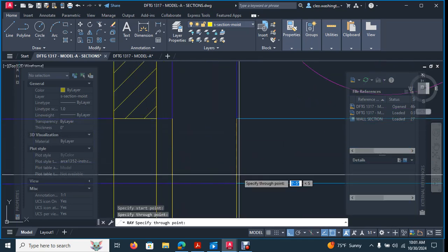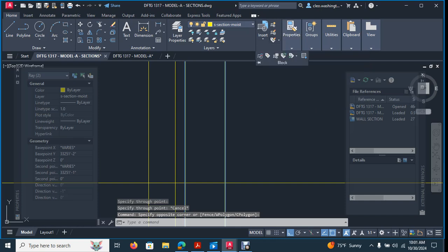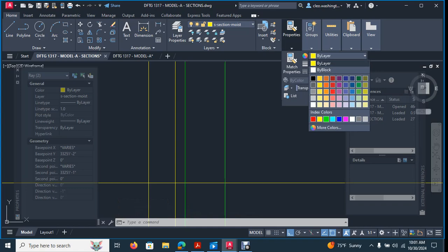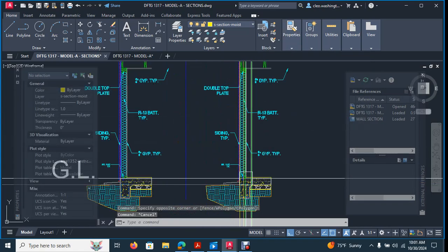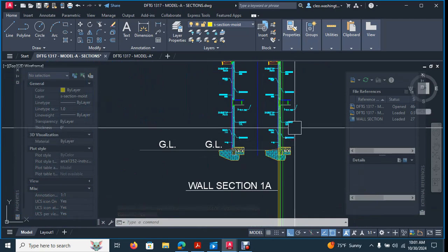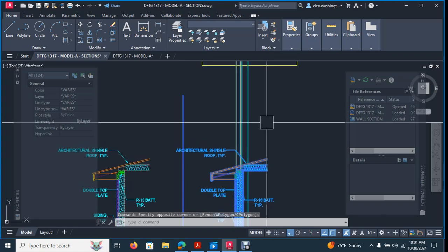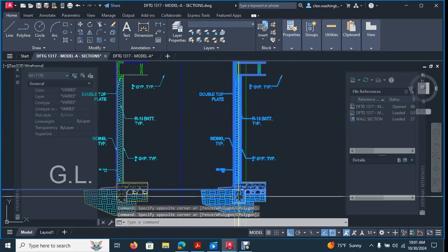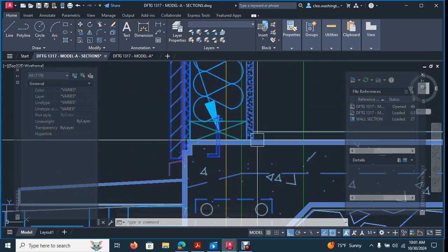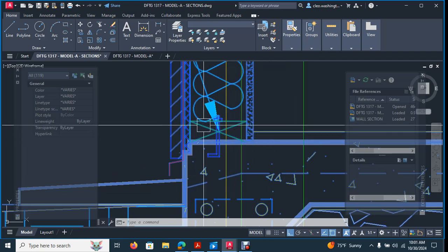So that's our brick wall, and this is our interior wall, RAY. So what we'll do is we'll line things up based off of this interior wall. Let's change these lines. Let's change this color to green, okay? Now we know the green lines, that's our interior wall. So let's take this wall section right here and hold down shift to deselect any lines that you have selected. And let's move the actual 2x4 stud into the area where it actually should be.